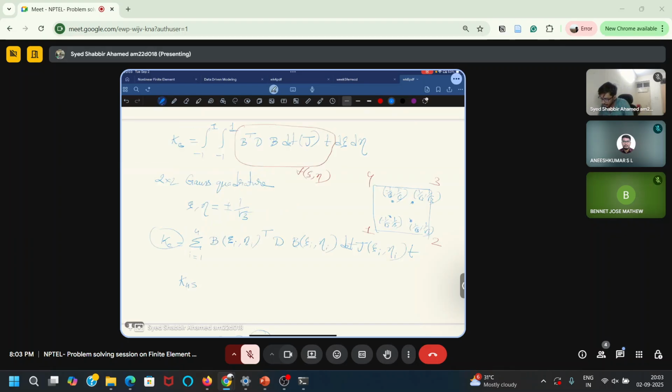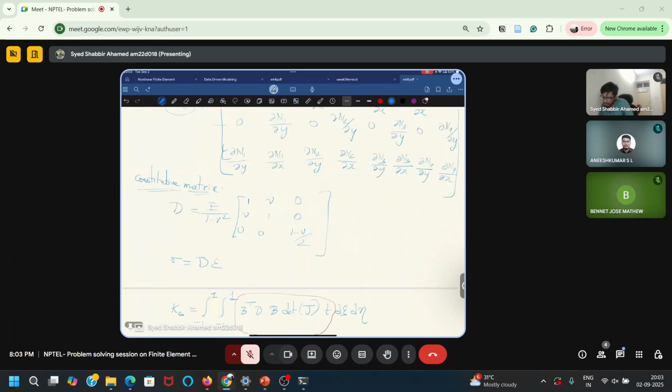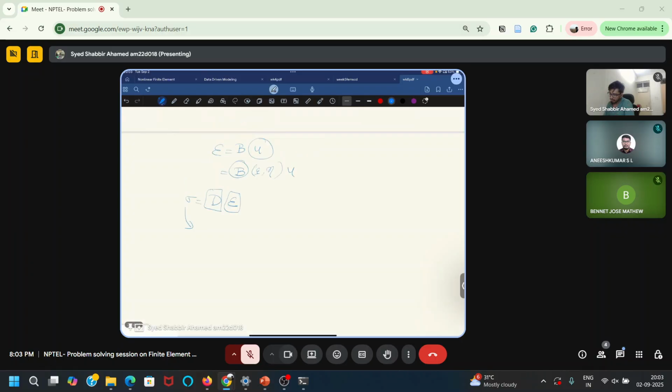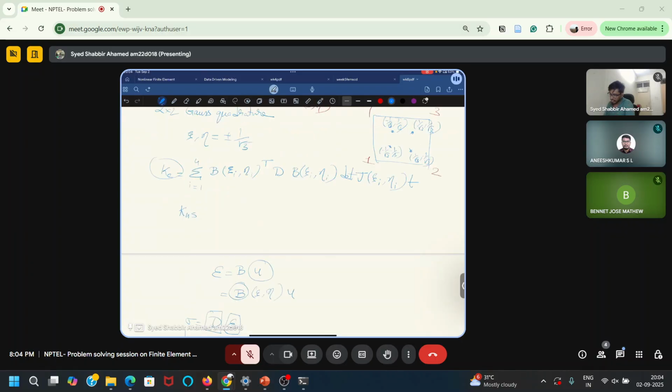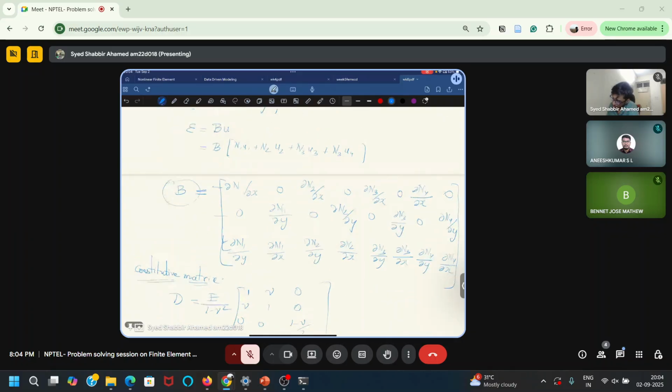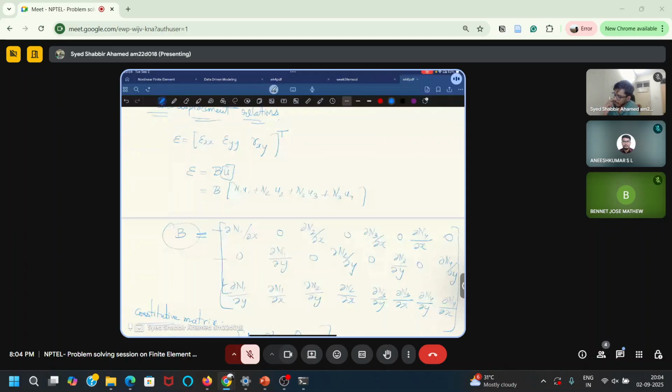See, the K matrix is a separate question they have asked. There is no relation between K and sigma here. Can we find the stresses without the K matrix? Yes, we can, because they have given U here. In the question, they have given 8 displacements. That is the U vector.